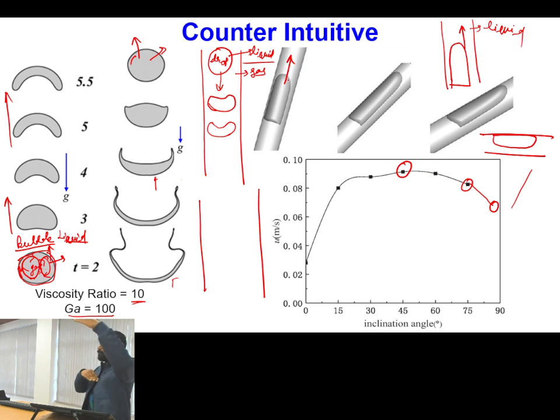The tube is closed from both bottom as well as from the top. So this bubble is going up, so this much volume of liquid should move from top to down. So liquid will be counter-flowing in the downward direction in the form of a thin liquid film. Okay. So of course, when this thin liquid film is moving down, it will produce some amount of skin friction drag, and because of the shape, some form drag over this. So ultimately, drag force will be acting on the bubble.